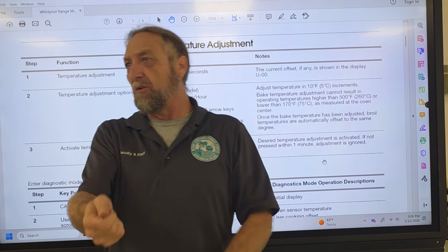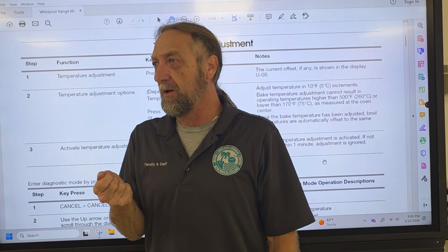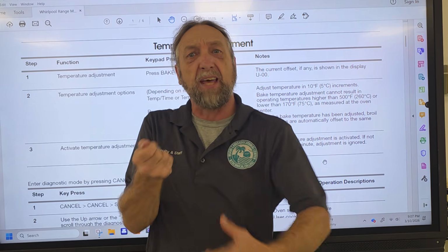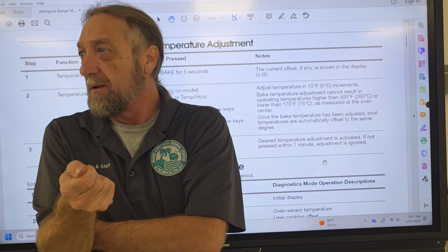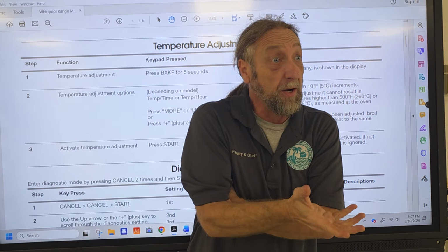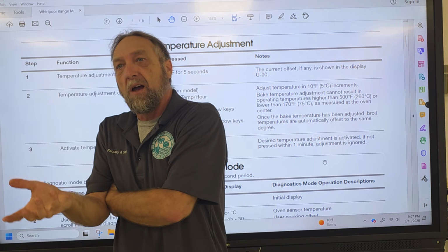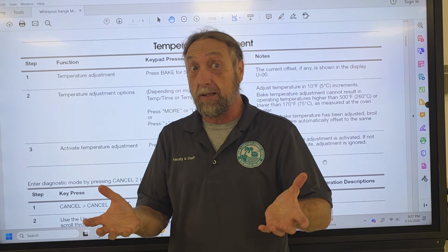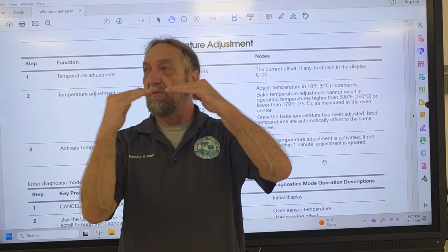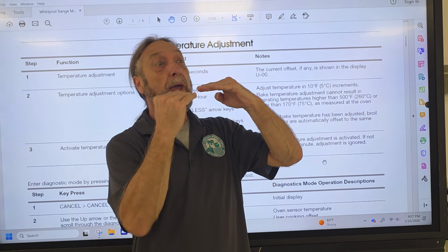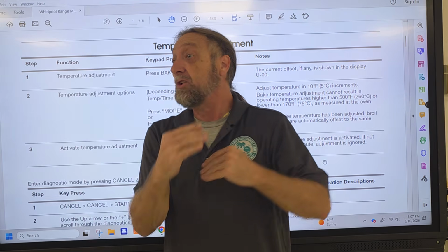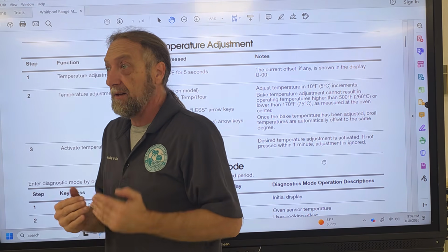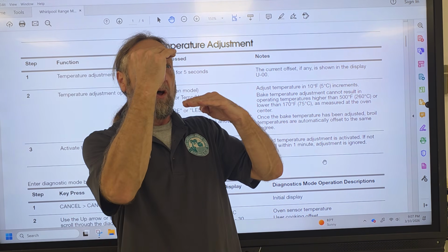No. If you take a frying pan off the stove and I hold it for 2 minutes and say, here, touch the pan, would you touch it? No, because it's still hot, right? Very hot. So when the power's turned off to the element, they're still radiating heat. So even though it's set to 350, it way overshoots that 350. It could go as high as 370 when it overshoots, okay?